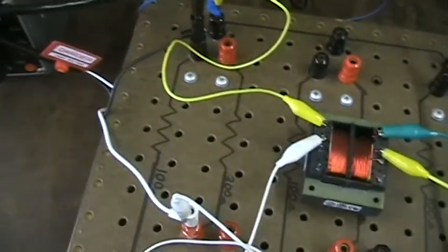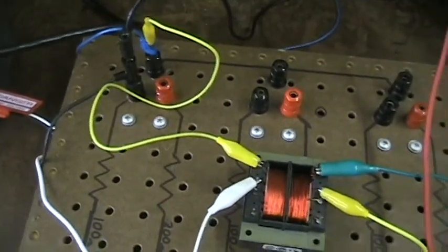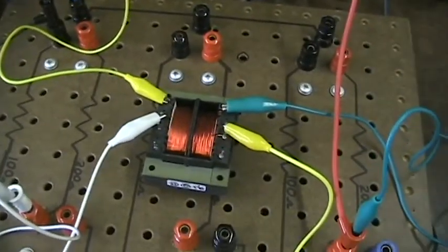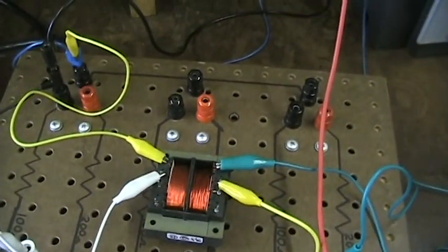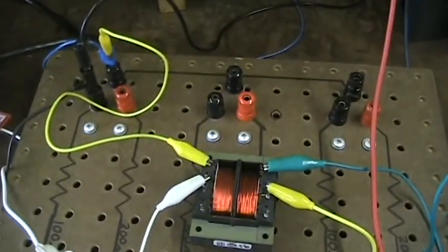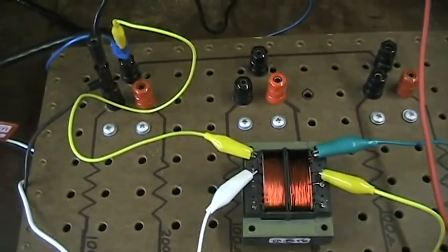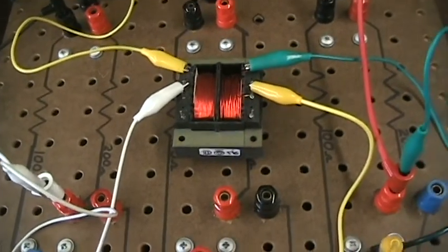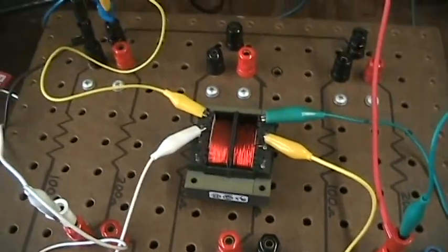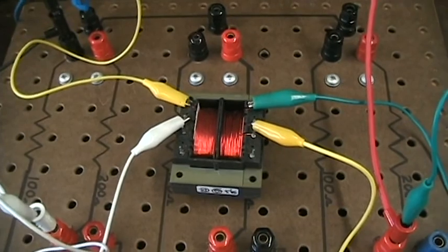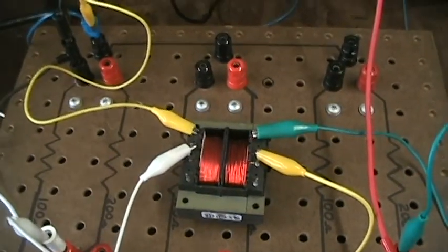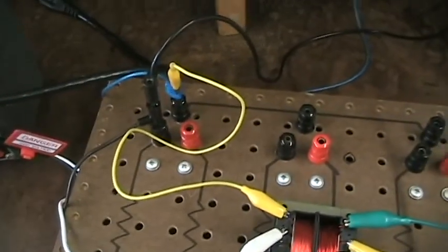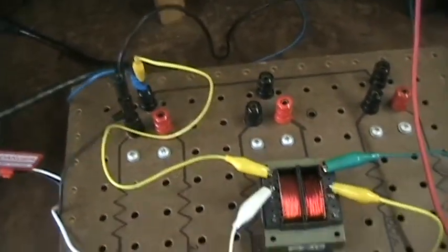So for the next part of the experiment, we're going to collect current data. As I've told you, my preference in taking current data is certainly to measure voltage across a resistor and then divide by the resistance to get the current, but that's not always possible to do. And so in some cases you must break the circuit. So that's what we're going to do in this part of the lab.